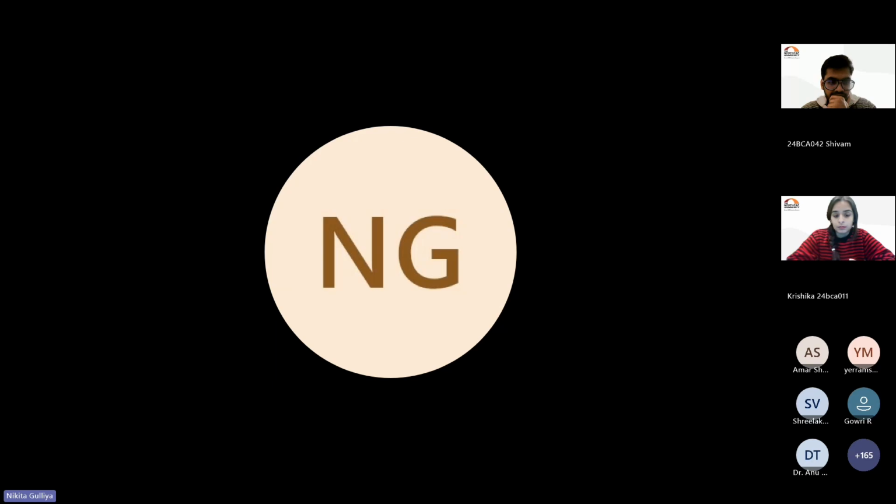You can take that Verilog output onto EDA Playground. EDA Playground is also open source. In EDA Playground, you can check its simulation to see whether that Verilog or the UVM code is correct or not. And then that can be further taken to ModelSim to do the simulation. So at least your front end part is done through open source.